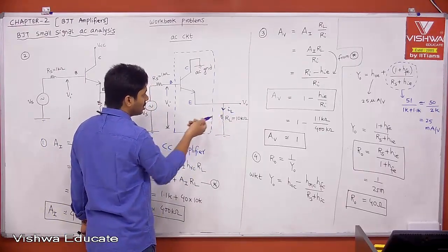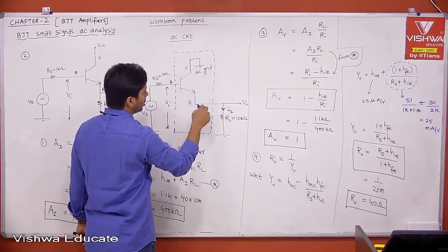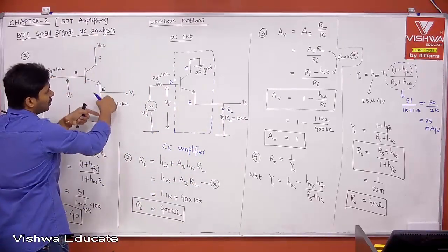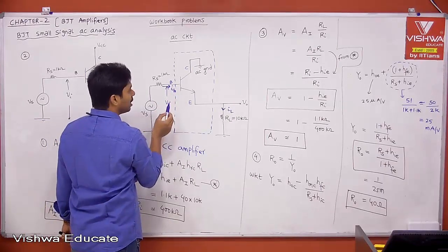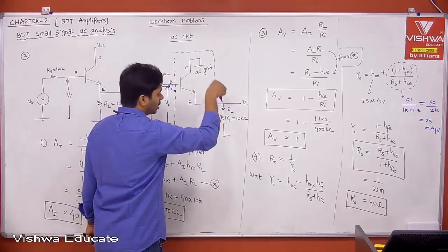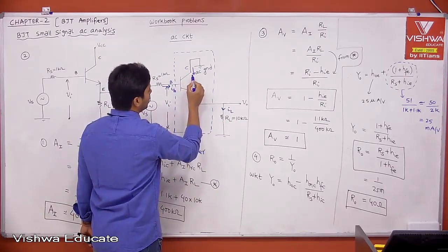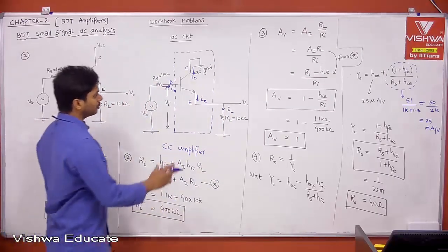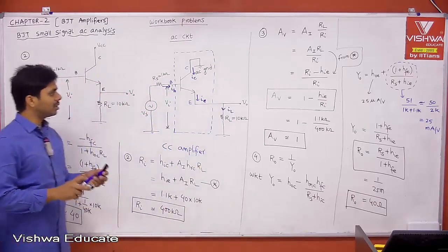Is this the real direction? Yes, because this is base current, this is collector current, base current plus collector current, that is not your emitter current, that is what is entering into your load, right? Therefore, base current plus collector current is what is entering into your load. The base current also is your input current IB, let us say. Therefore, your input current, the current which is entering into your amplifier, is satisfied. The current which is entering into the load, IL, is satisfied. Basically, that is nothing but your emitter current, right? Because IB and this is your IC and this is your IE. Then your IE is nothing but your IL, satisfying the direction, right?